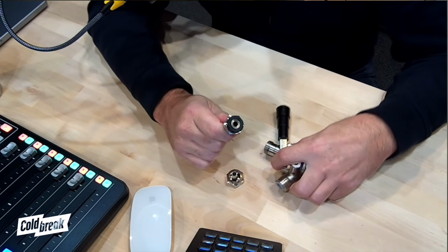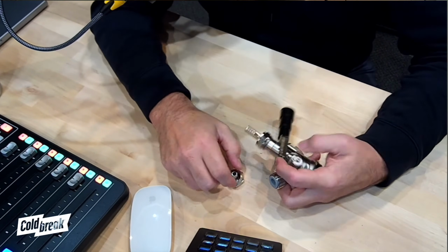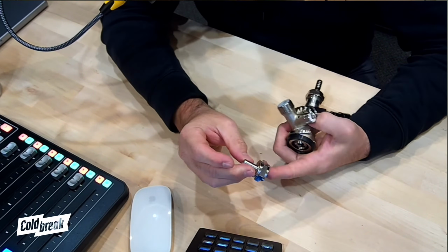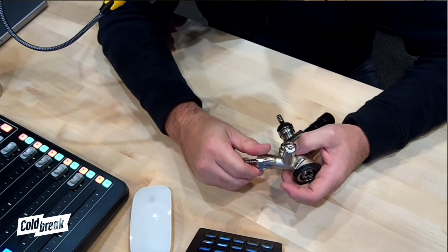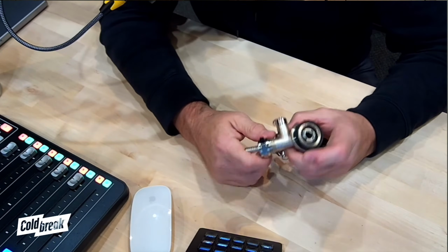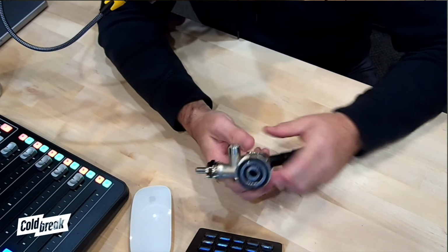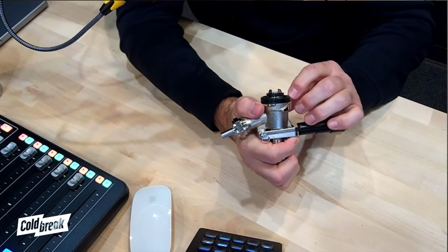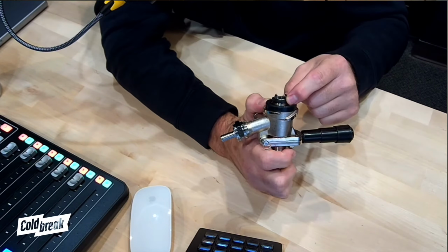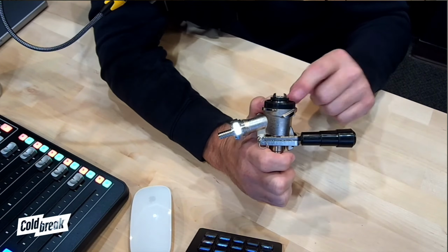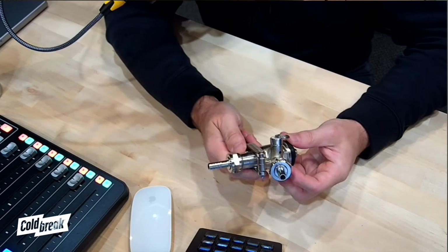You don't typically need a beer washer between your gas side and your gas tailpiece here because the check valve acts as its own beer washer. Down below, there's another washer because it's metal on metal. This one attaches to the keg. And then again, there's another washer in here that goes above the ball that you push down on the keg itself. So there are a couple other washers in here that will eventually fail. These can be replaced easily.